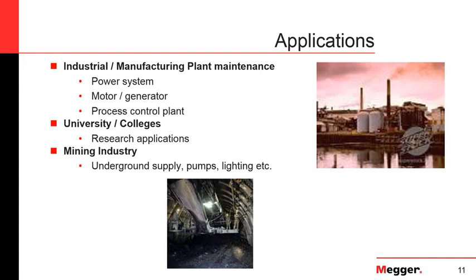But let's say we have a problem in one of the junctions in that bus bar, and the resistance changes to 100 micro-ohms. One may think that change is not significant, but at that level of current, if we calculate the power dissipated, it will go up to 14,400 watts.